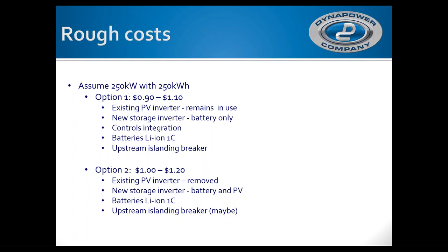Then I need at least a 200 kilowatt battery inverter, so let's round up and oversize it slightly: a 250 kilowatt battery inverter. So the power here is 250 kilowatts. That's how much power I need to supply the critical load in the worst case.